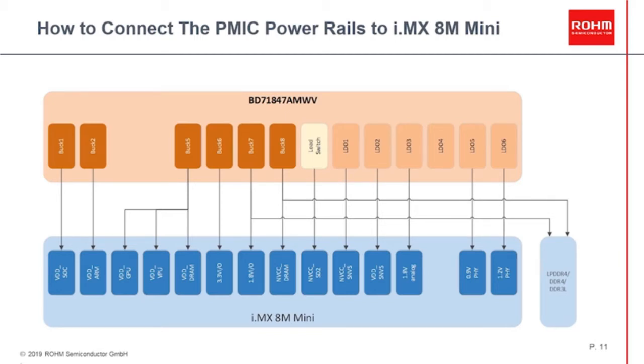BD71847 integrates one LDO which is not controlled by the SoC. This LDO4 can be freely used by the user and controlled via software, meaning the I2C interface.